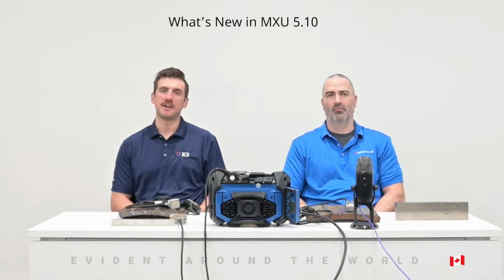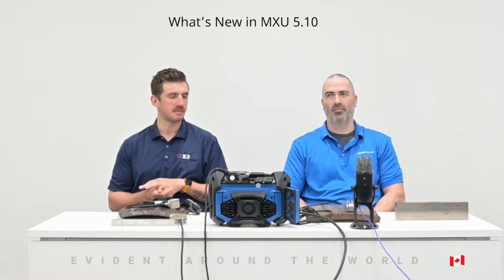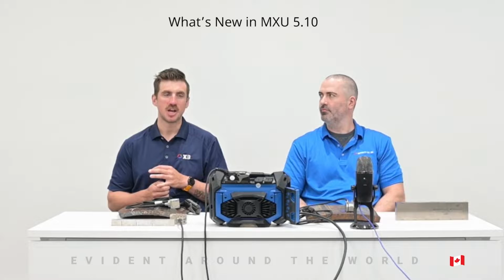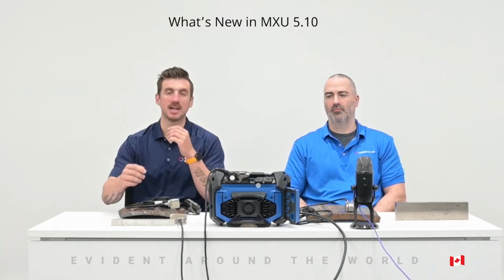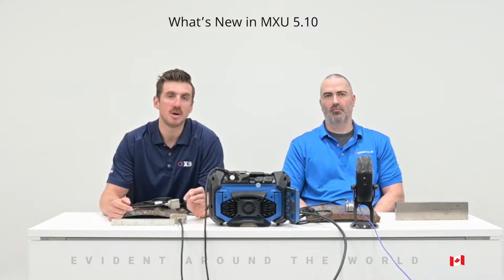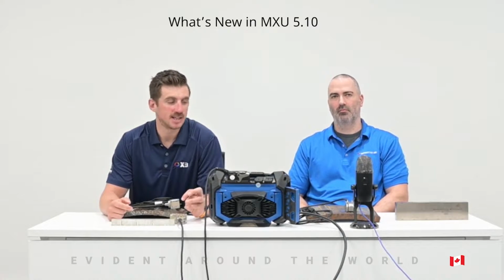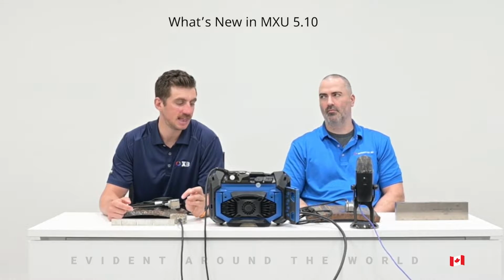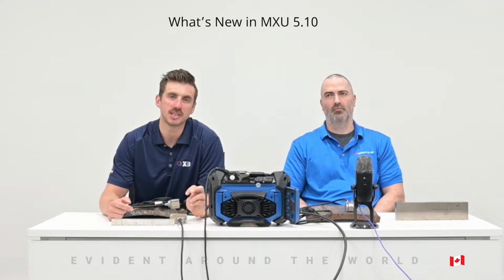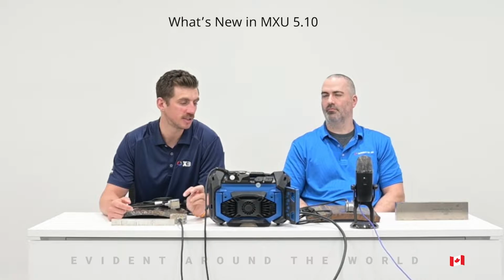PCI is going to be a variation on TFM, and rather than using the amplitude, we're going to use the phase information of our A scans to generate our image. The big advantage with the Omniscan X3 64 is that this image is going to be a live image in real time while we're scanning. Phase coherence imaging is also going to be a lot more sensitive to small defects and less sensitive to large defects such as the back wall, creating a better signal-to-noise ratio in scanning a lot of materials, especially noisy or attenuative materials such as austenitic steel or stainless steel.